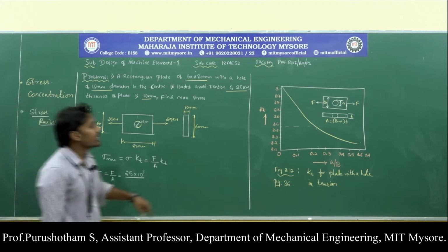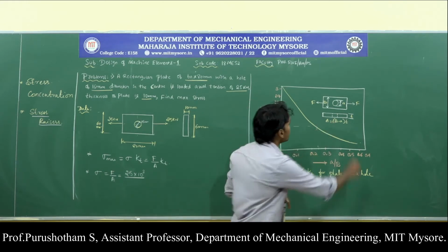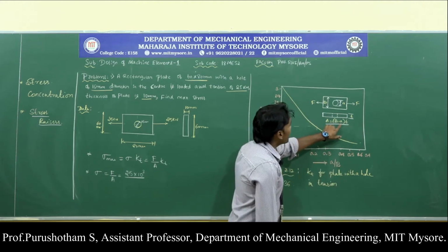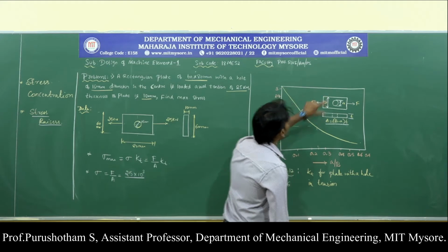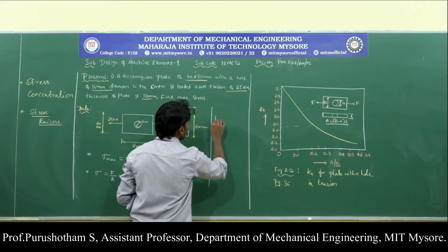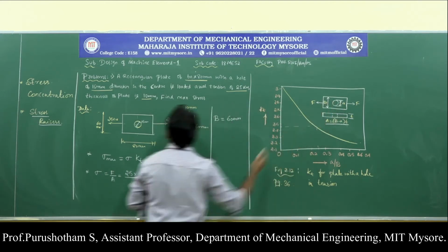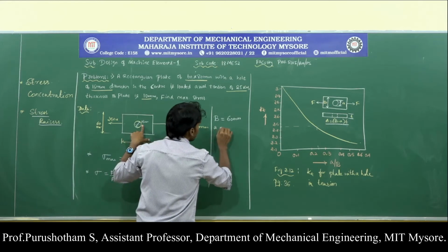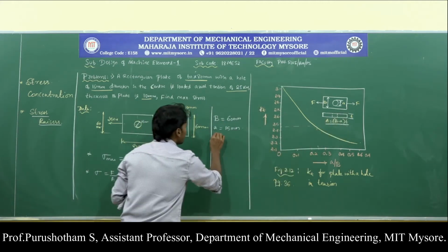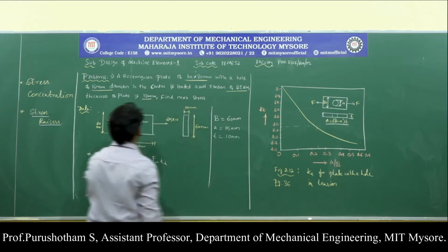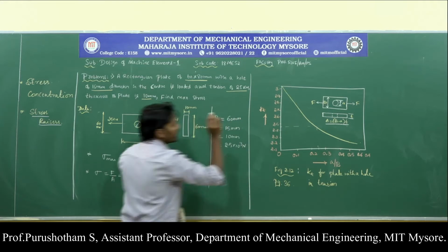Then to calculate the area, in the figure itself they have mentioned how to calculate the area. For the rectangular plate with a hole, they have mentioned the equation to calculate the area, that is B minus A times T. So first I will identify the B value, which is nothing but the width of the plate, that is 60 millimeter, and the A value, which is the diameter of the hole, that is small a, which is 15 millimeter, and then the thickness value, which is given by notation T, which is also 10 mm, and the force, for which they use notation F, which is 25 into 10 power 3 Newton.